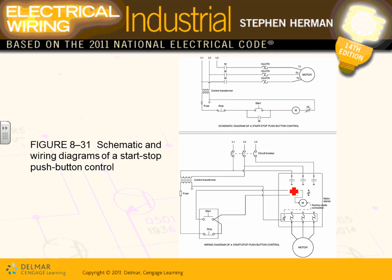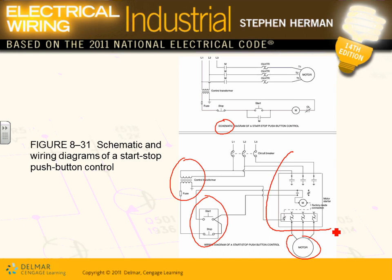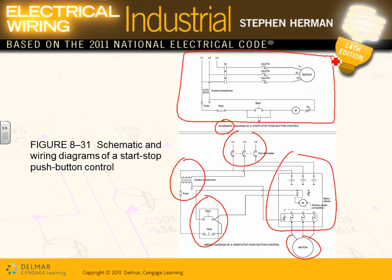So here are your schematics, looking at the top. Can you guys see the schematics here? And down here, you have your wiring diagram. Look at the components that you're wiring. I have my transformer, my push button, my motor, my magnetic starter right in here, and my source. Can you see that these 5 things are different, separate things, and they're all interconnected, compared to the schematics, which really don't care much? They show them all in their sequential operation, how they are interfaced with each other.